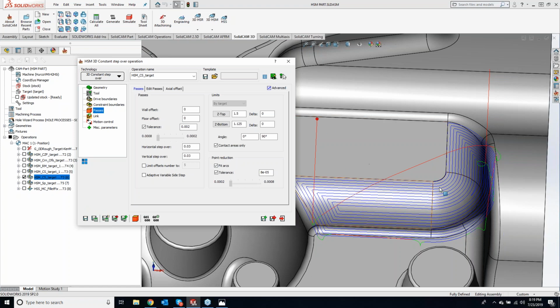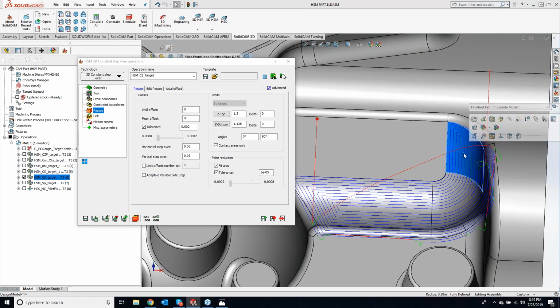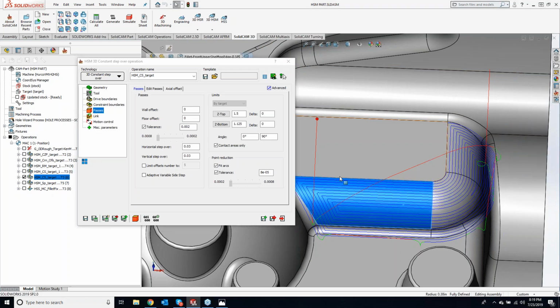Now, if I was to do this with HSS, like I was just telling you guys, I would use morph between boundary curves, and we could come in here and grab this, and I think, no, I didn't set one up on this one. So I would do our HSS, grab these three surfaces, and do that as well.